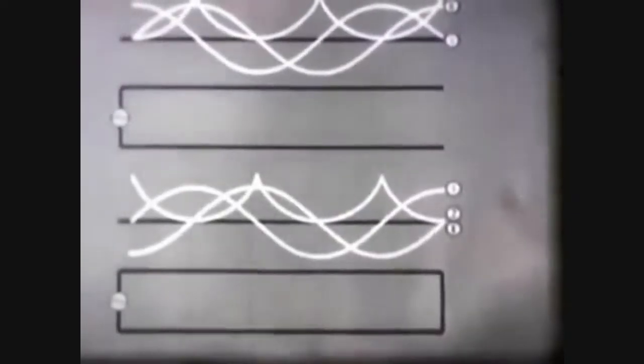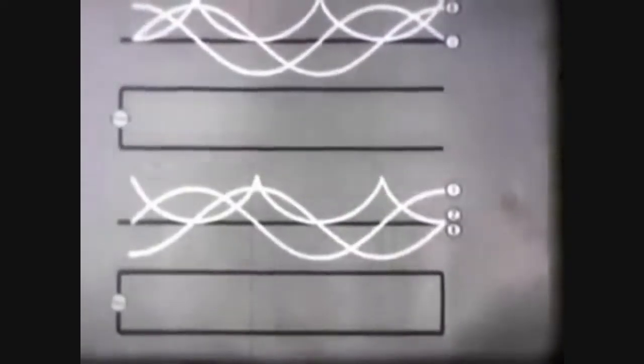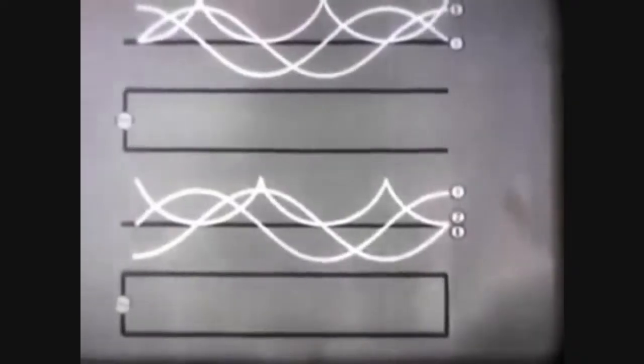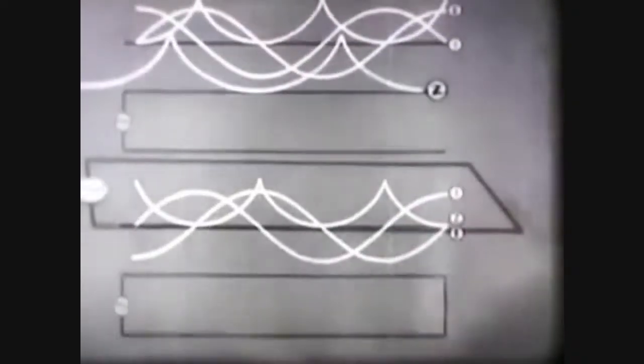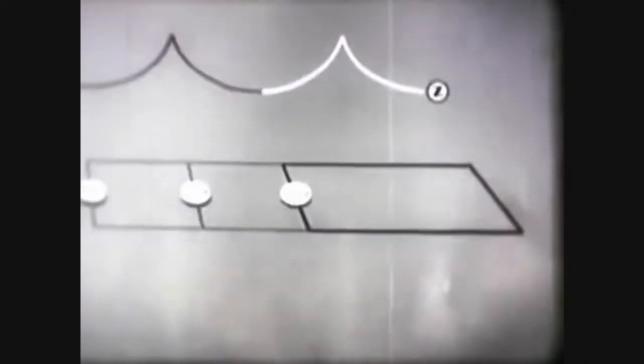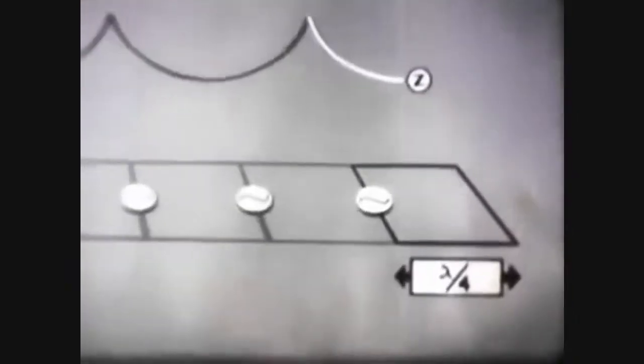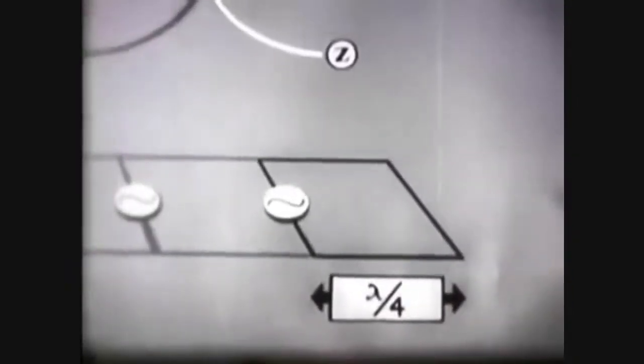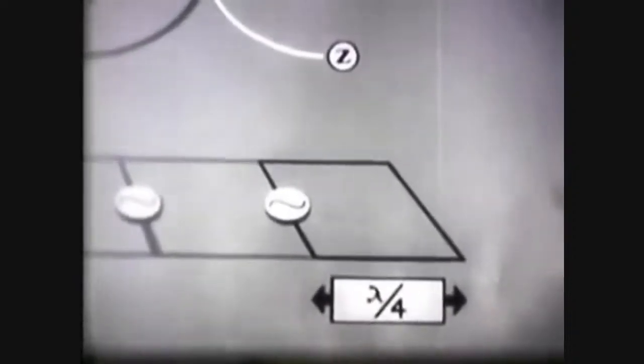How does this apply to radio antennas? Well, let's shorten our closed-end line and find out. Now we're working with only a 1/4 wavelength of a closed transmission line. The impedance at the terminals of the generator is maximum. In other words, the generator sees the circuit as one of maximum impedance.